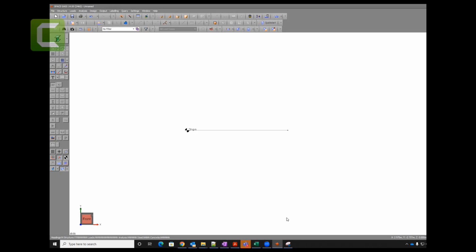This is another point. Unmute yourself if you fall behind. What did I do? I clicked draw members. I did not do anything else. I pressed 0 on the keyboard. Keep it horizontal, and I pressed 3 on the keyboard to make this 0 to 3 meter long member, which is exactly the same as what you see. Now we draw the next member.